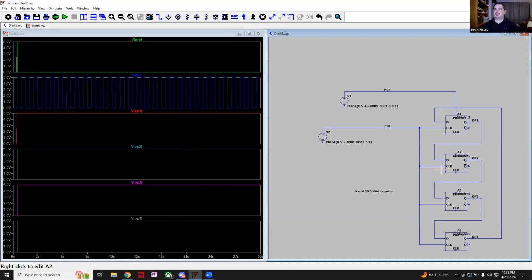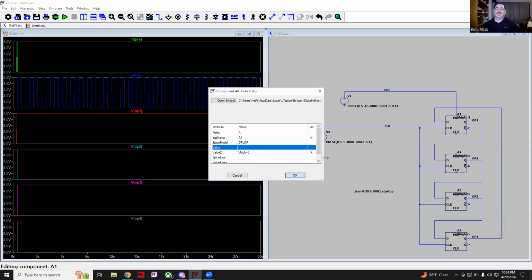Well, that means the clock source had to be in its rising time, and the input had to be on 1, and then on 2 and on. Well, that's not how actual integrated circuits work. They don't push the voltage through immediately. There is a slight delay time as the electricity flows through the integrated circuit. The simulation doesn't do that for us automatically. You actually have to give it that command.